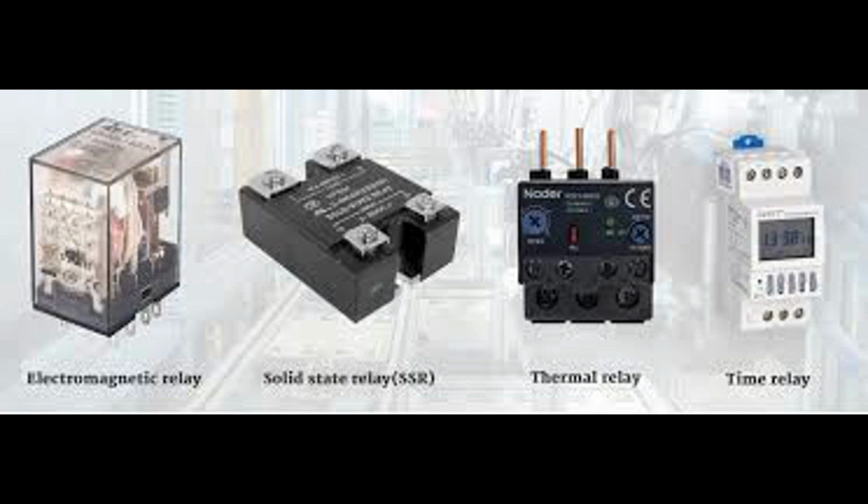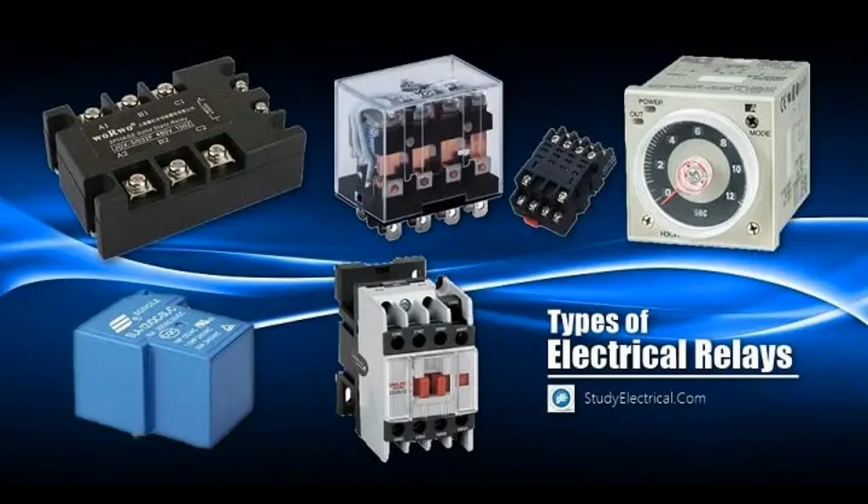Structure and components. Current transformers, CTs, are placed on both sides of the protected equipment, e.g., transformer primary and secondary sides, to measure the currents flowing into and out of the equipment. Comparing circuit. This circuit compares the current values from both CTs. It is often an internal part of the differential relay or protection system.